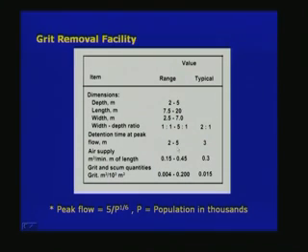grit chamber, and the typical value is 3 minutes. So, normally if you want to design a grit chamber, it should be designed based on this 3 minutes detention time. Okay, 3 minutes is the detention time.